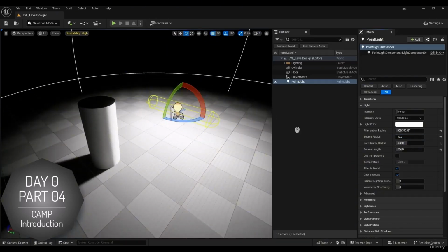There's another option too, that we can use temperature to define whether our light color is warm or cool light. It's a very useful option, and we don't care about the rest of the items for now, and the things I told you are the same in most lights. Let's test it together now. Well, we learned how to use point light, what settings it has. Be sure to practice this thing I told you yourself. Work with it a little. Since it's real time, you will easily get the hang of what is happening.